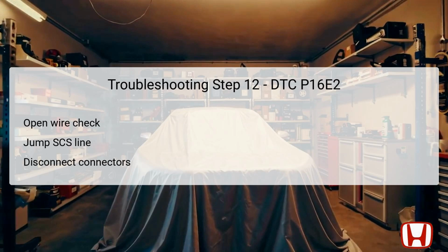Otherwise, a diagnostics and repair request for an open wire in the system between the alternator and A10 of the PCM becomes crucial. Moving on to step 13 in diagnosing the issue surrounding DTC P16E2, you again check the possible failure area while measuring the alternator connector.